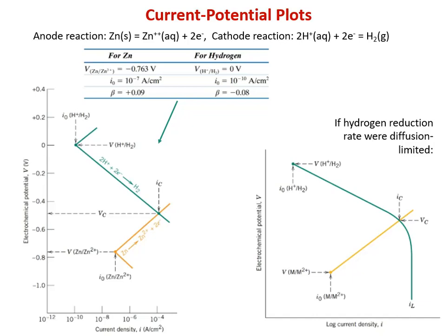So we might want to look at the relationship for these two different conditions, and we can plot the driving potential, the electrochemical potential, for half-cell reactions, because we'll tend to look at these in terms of differences in anode and cathode. They tend to operate under different conditions. So here we have electrochemical potential plotted on the y-axis.